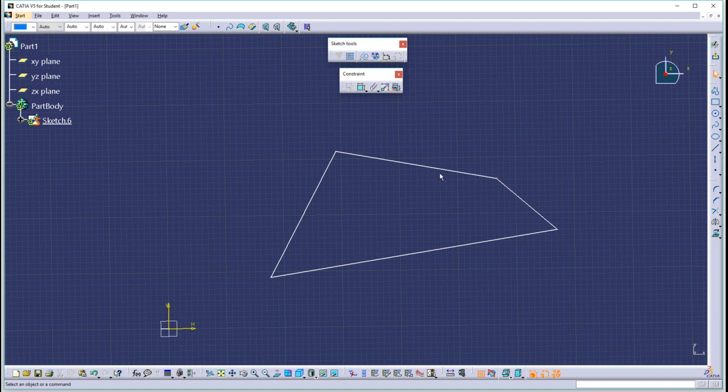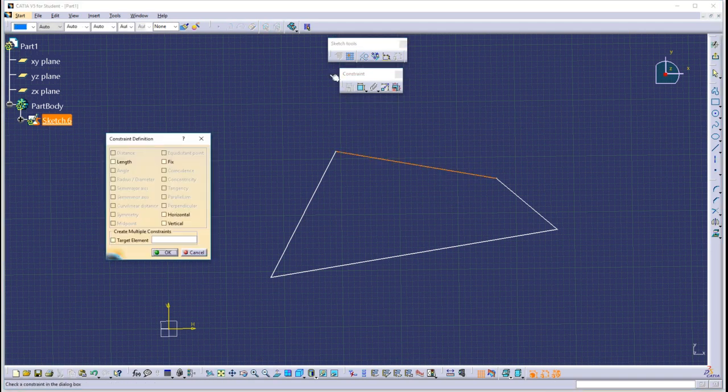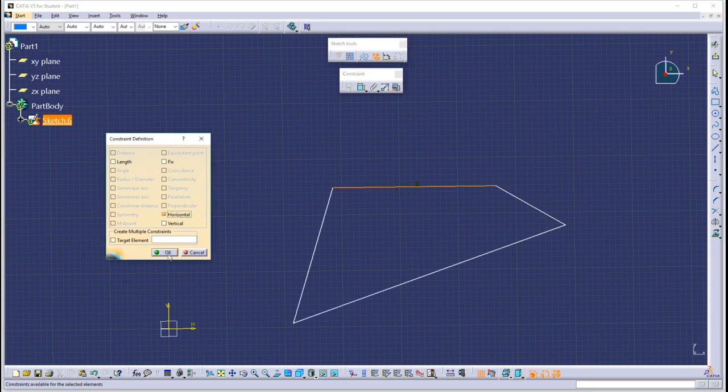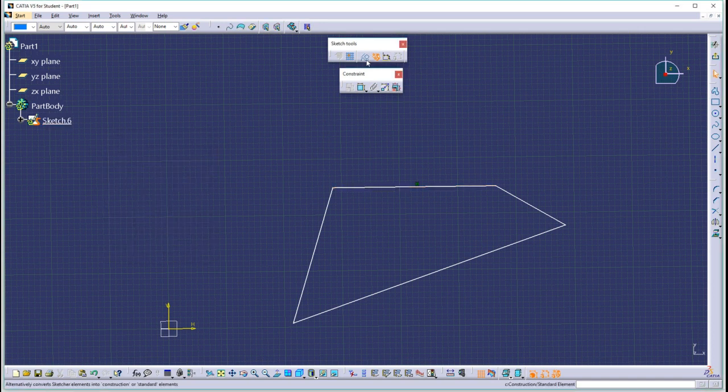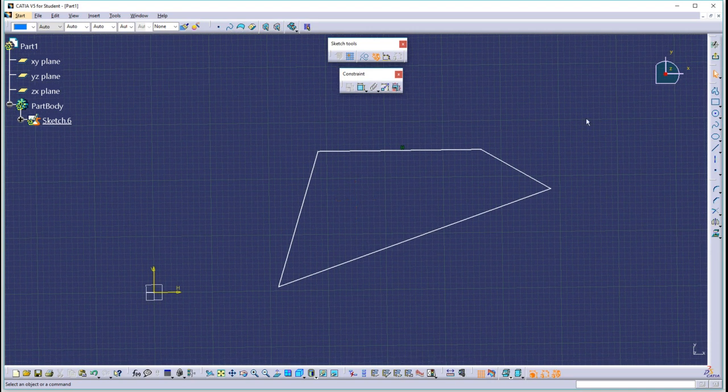Let's do it again. Pick this icon. Except this time I'm going to come up here and turn on the geometric constraint icon. This will make it permanent. So when I say horizontal, it's horizontal. No warning box, because it's now telling me that you have this turned on. It will stay horizontal. And in fact, you can even multi-pick things.